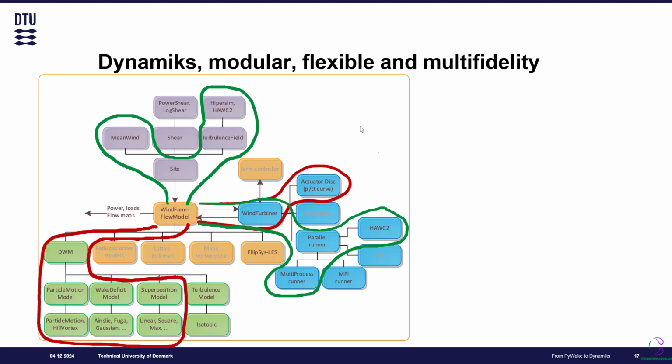So you can now see the further expansion here. For the wind turbines, it's not only one approach, not just the actuator disc that is being used. You are now using other types of wind turbines. Real world wind turbine configurations are being used for this analysis, which will also give you different kinds of results as opposed to just using a basic actuator disc, which may have different behavior when compared to an actual real world wind turbine.